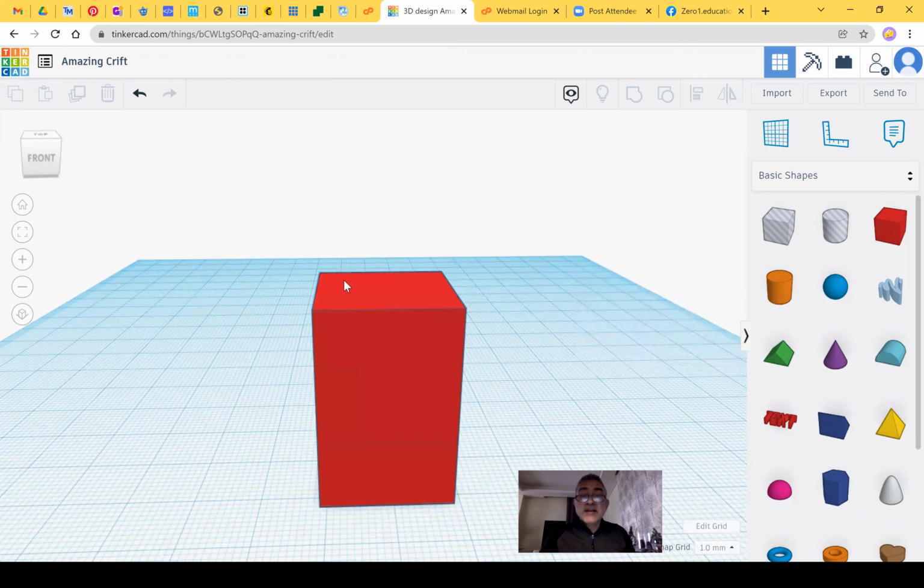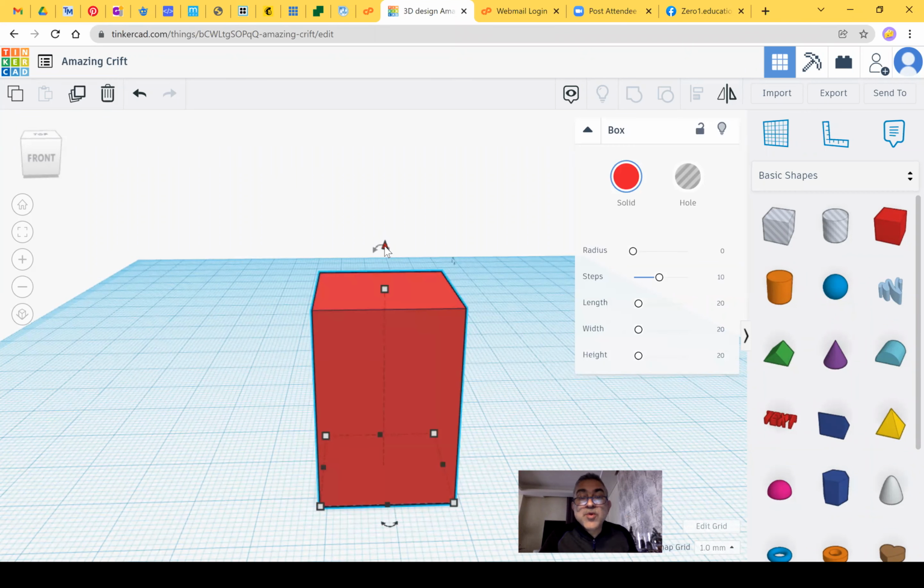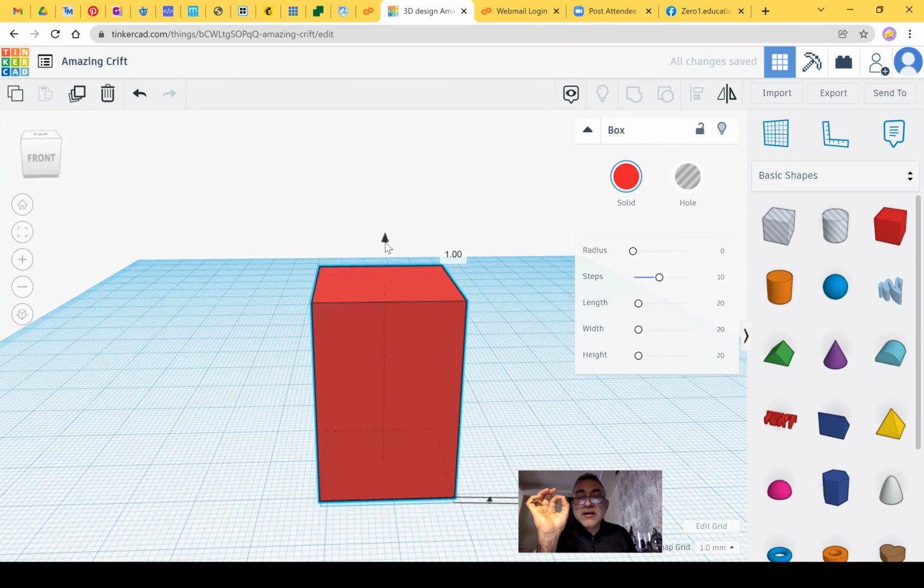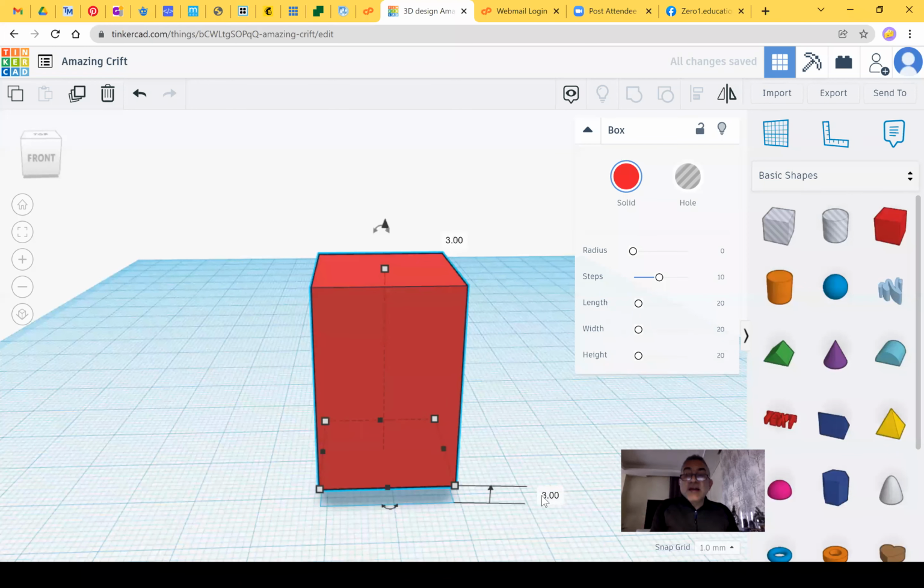And finally, you have a small black triangle. Once you click on this triangle, you can move up your mouse, and of course you can see what we call the elevation from the work plan that you can modify.